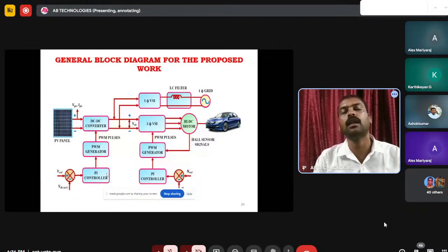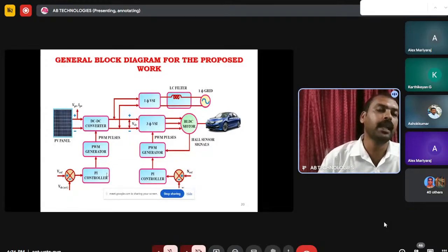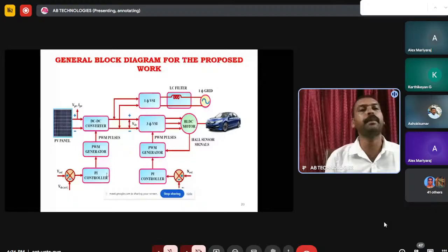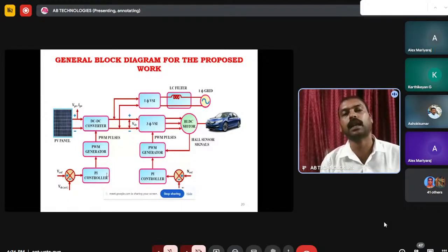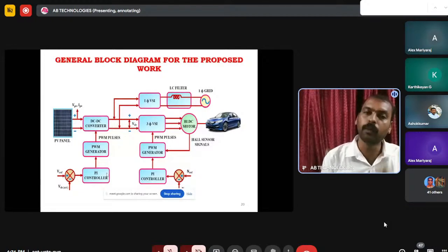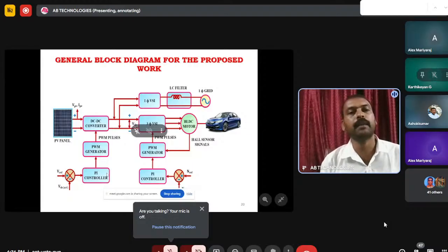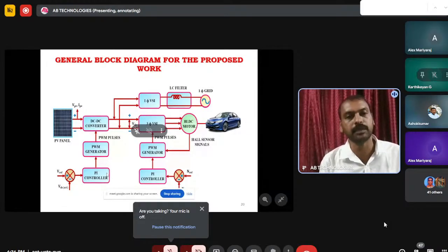In a conventional DC to DC converter, first it has one inductor and capacitor. Passive losses are very limited. But the voltage gain of the conventional converter is very, very less. That means your input is 12 and output is 18. So what is the gain? Gain is Vo divided by Vin. So 18 divided by 12, you will get around 1.5 times.